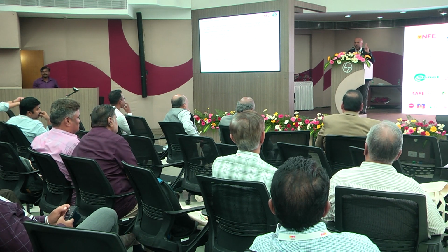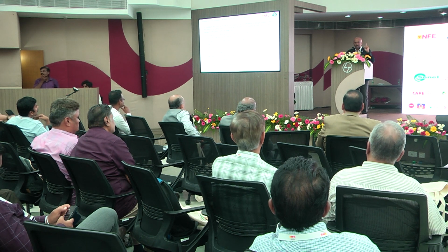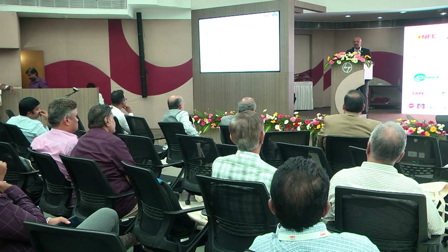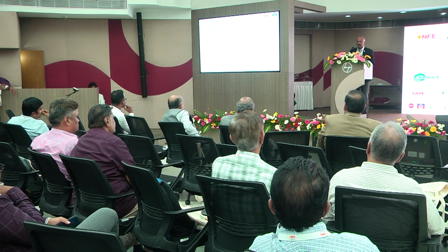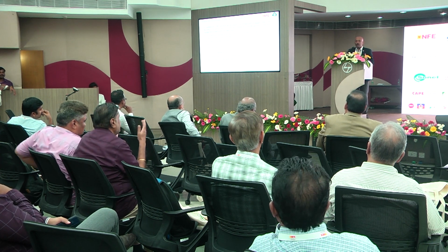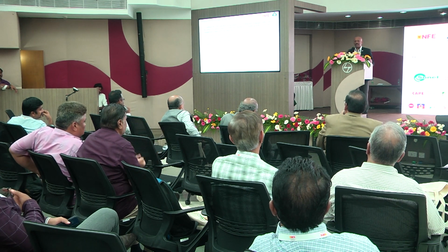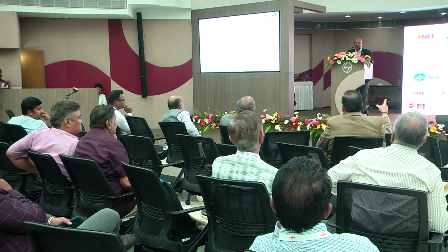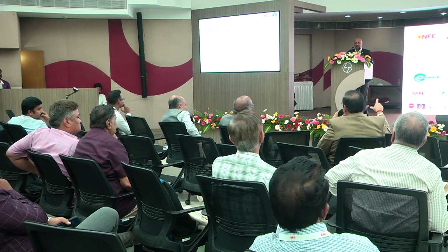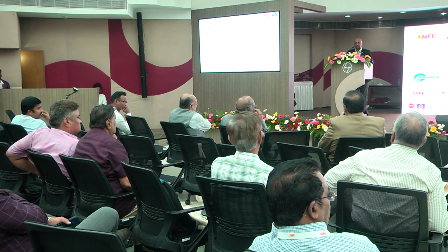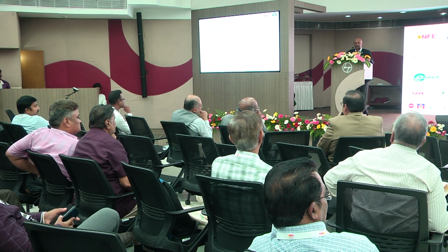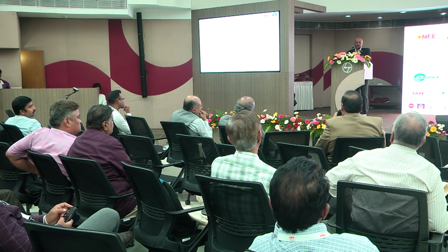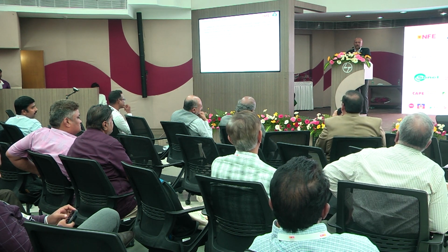No, sir, please note that you can handle it in two ways. If you know that your panel is going to have high temperature, first, you rectify. If you don't want to rectify, then you put a suppression system or something like that. That's what he's explaining in two ways. One is this testing, whatever testing they're saying, making it mandatory every year. You can find out certain things like this and rectify. That is one way of doing it. The other way is, as NBC specifies for main panels and other things, use gas suppression wherever the heat goes up. You have the suppression system working to protect from fire. So these are the two ways.